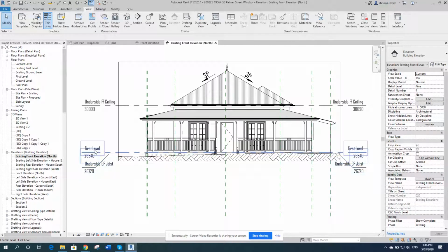levels as well. So if we're raising this house, then that's a whole another process of doing it, because Revit runs off of levels. The way we need to do it, that we find the easiest, and people do it differently, is to draw the house, don't show the number on here for the level height, draw it at the height that we're going to be at, so we work that out, and then we will copy the topography up.